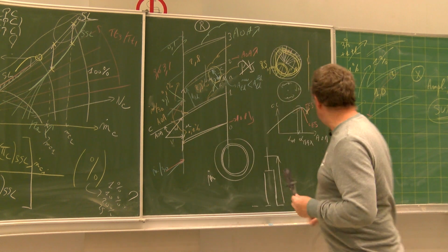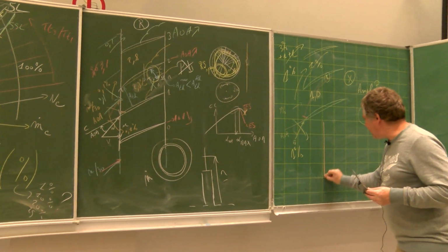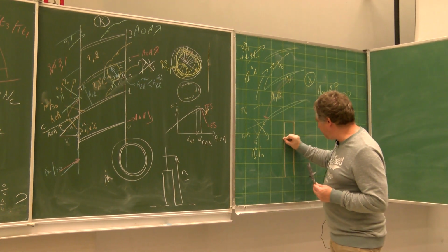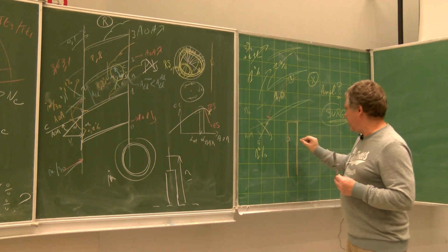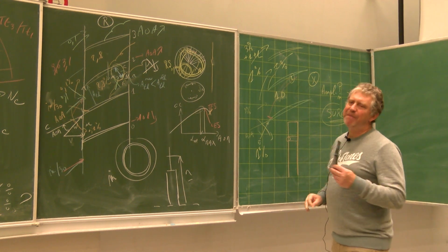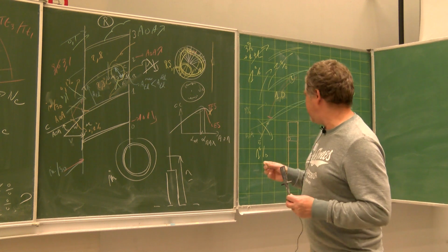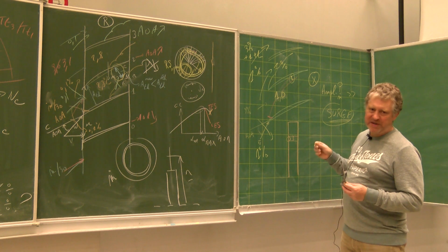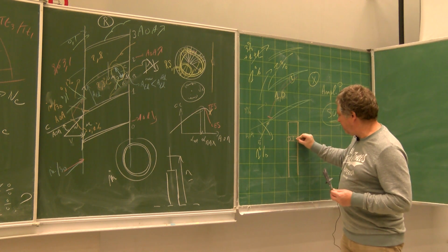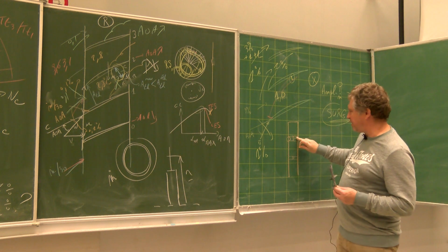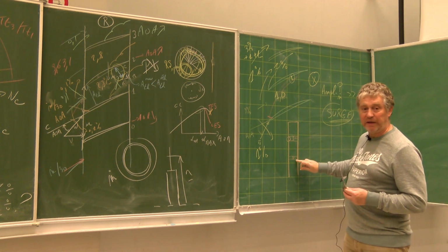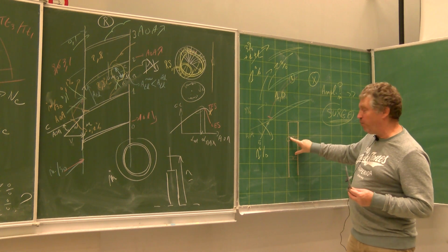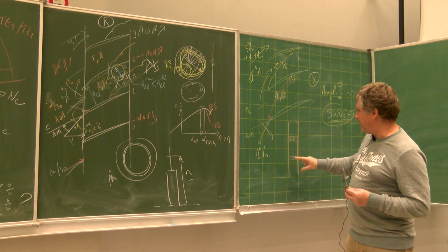So, if you have a long blade, I'm explaining it like this, and if you impact the blade at this position, so you see it's a problem of mass flow rate. So mass flow rate, this is not proportional with R, this is proportional with the surface, and this surface here with the same R here and there, this surface is much larger than this one. The surface of this ring is much smaller than the surface here. So you have much more mass flow rate passing here than there.